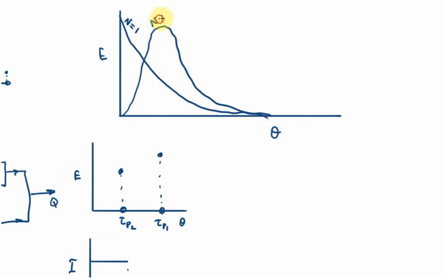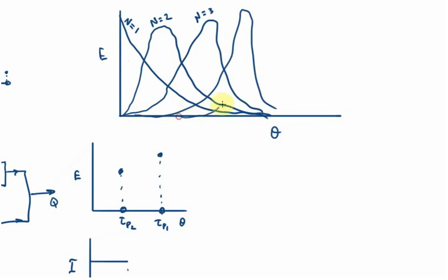So this is n equals 2, and then 3 tanks looks like this, n equals 3, and then 4, and actually as you go 5, 6, 7, you start to get this. You start to get a long 0 here, a sharp peak there, not perfect 0, a number close to 0. Then you get a peak up here, and so this is n tending to infinity. So this is your tau here eventually.